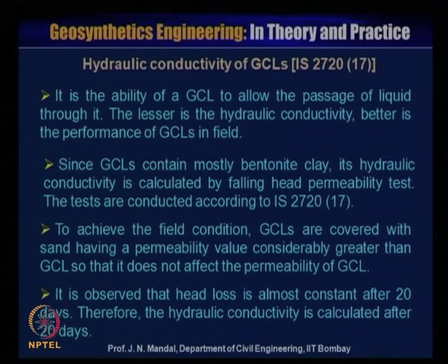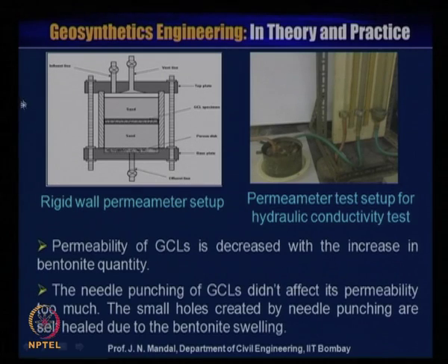To achieve field conditions, GCL is covered with sand having a permeability value considerably greater than the GCL so that it does not affect the permeability of the GCL. It is observed that head loss is almost constant after 20 days. Therefore, the hydraulic conductivity is calculated after 20 days. So, here is the rigid-wall permeameter test setup for the hydraulic conductivity test.